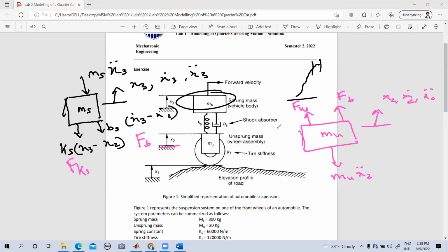So we are considering an occasion where the displacement is upwards, and the stiffness of the unsprung spring is holding this back. It's trying to go up and it's holding it back, so we'll just consider that force. It should actually act on this particular axis, but since that's going to be a little bit confusing, I just drew it right here. This is actually wrong. This force has to be co-linear with that, because the resultant of these two forces is going to be somewhere around here.